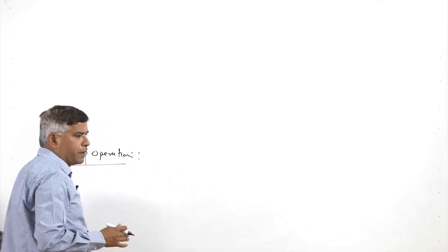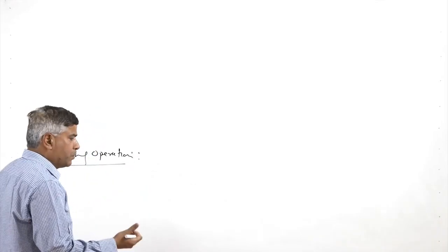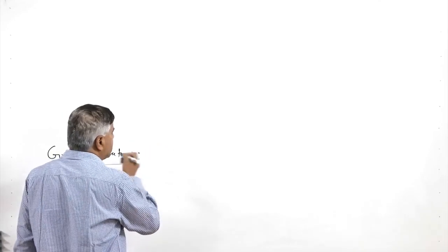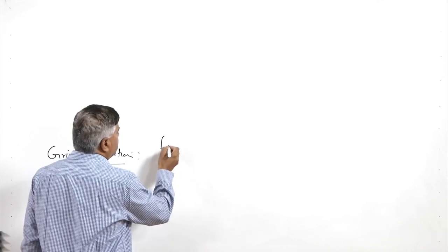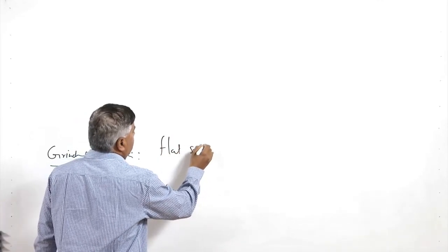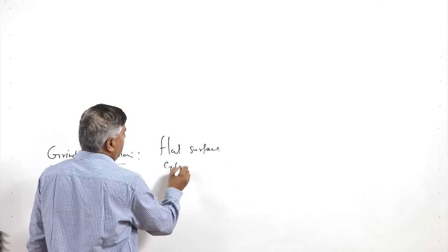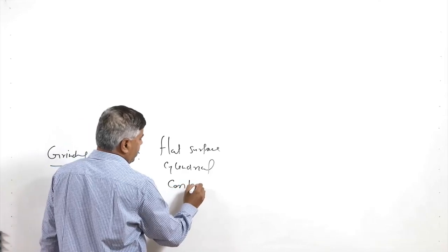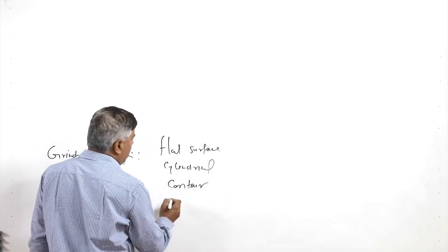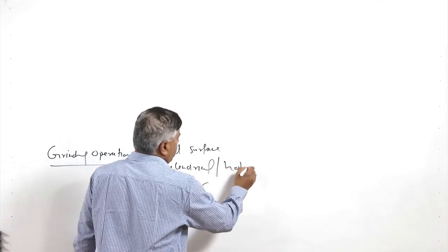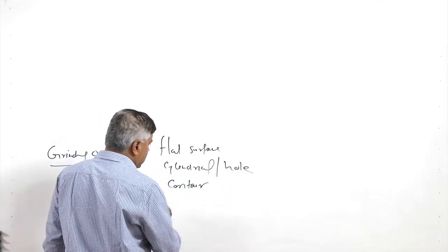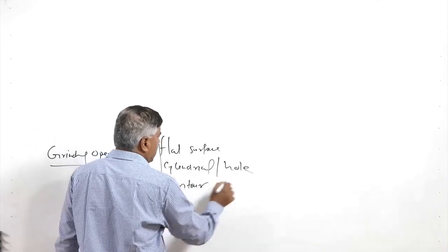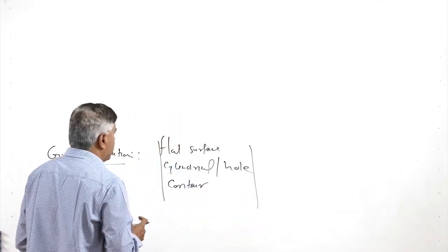The grinding is used for giving the desired finish as well as the control over the dimensions so that accurate size products can be made. But this is used for smoothing or finishing of the flat surfaces, cylindrical shape components, contours in form of threads, maybe holes, and gears, etc., and various such kind of the geometries can be processed by the grinding process.